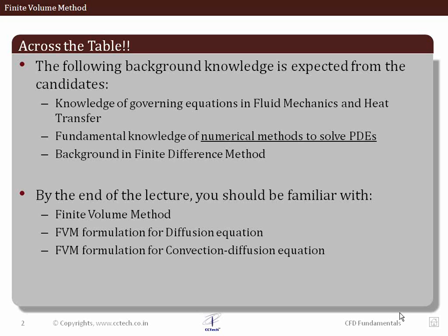What we would be expecting from you, having already gone through the lectures on fluid mechanics and heat transfer, and specifically the lecture on numerical methods, is how these numerical methods are used to solve the PDEs, and surely you have gone through something on the finite difference method, how a partial differential equation has been converted into linear algebraic equations. What we are going to look at today is more specifically the finite volume method, which is also similar to the finite difference method in that it converts the partial differential equations into linear algebraic equations.